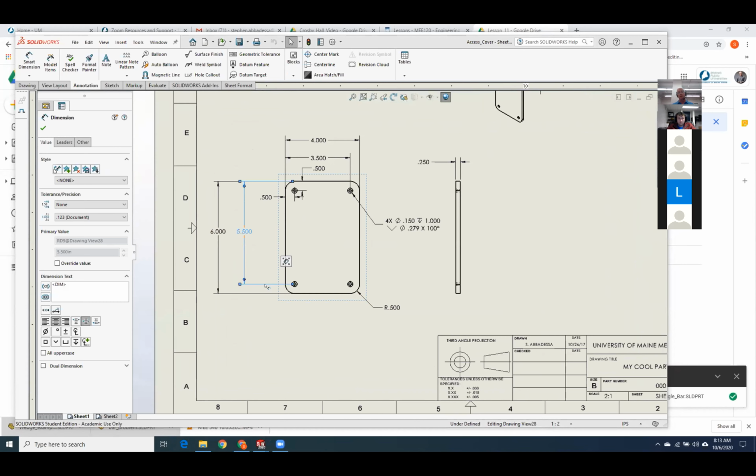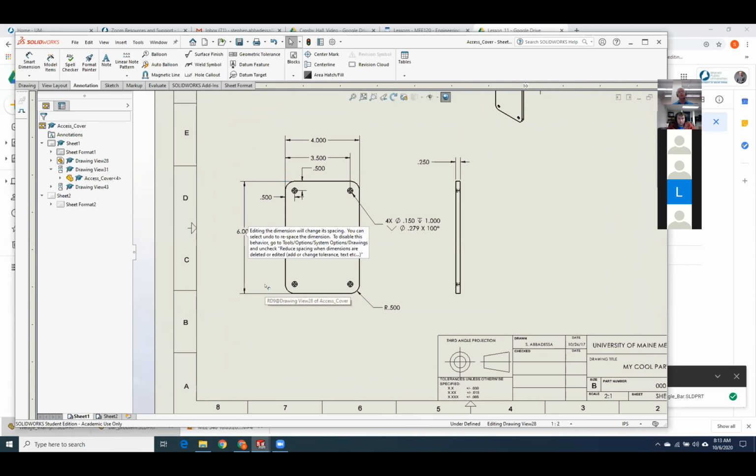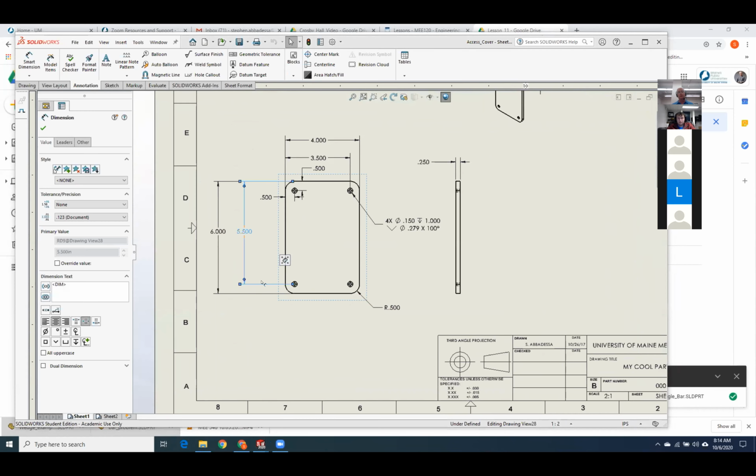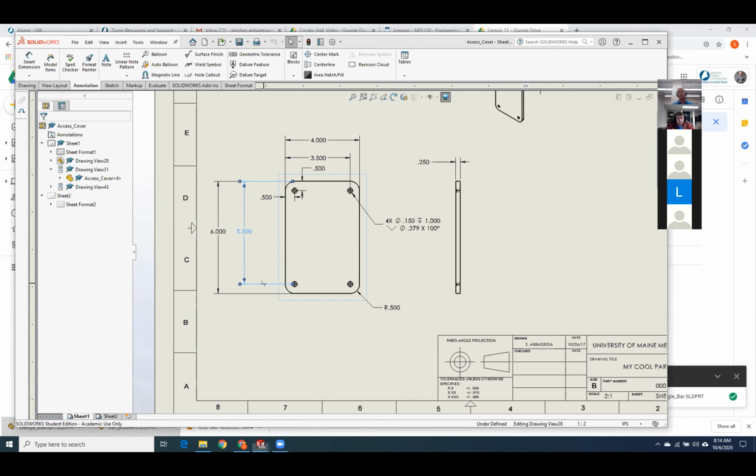Okay, so I'm clicking on the extension line and I press the delete key. But yeah, you're right. That should have come up with a delete option. So just left-click on the extension line and delete? Yes. So I left clicked, press the delete key, boom, it's gone.